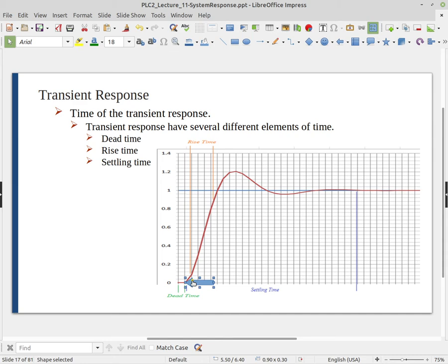So even if you're sending out the control every scan, there's at least maybe a millisecond for each scan to execute. At the beginning of the scan, we read in the new set point, but then we have to run through all the ladder logic, generate our control output, and then actually send it to the output before we see a change.